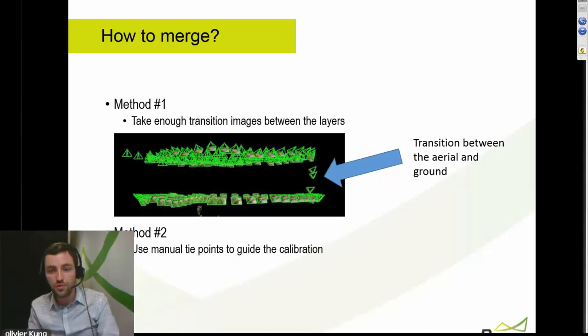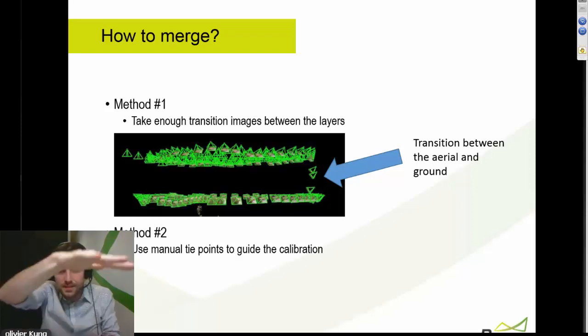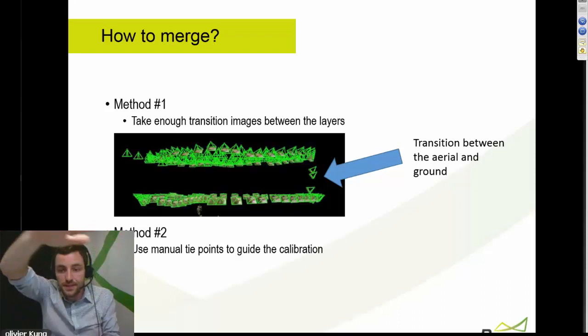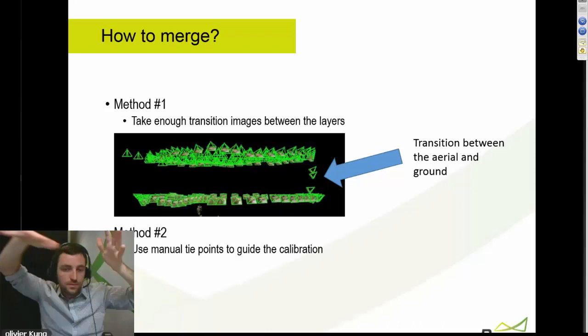For example, this is not possible to do with a fixed-wing drone, as you are limited in the pictures you can take. However, with a copter, you could take a data set as a nice grid from the top, and then slowly take a lot of pictures that will make the transition into a different point of view. And then you could start doing the project from the other point of view and do a full reconstruction there.